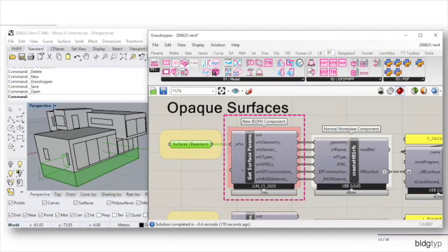This is going to be done by using a lot of these new Grasshopper components, and these things are used in line with the existing Honeybee components. So in order to extend and expand the basic Honeybee workflow, we're going to add some new functionality. For instance, when we create a new thermal zone, before you pass that geometry into the normal Honeybee components, we first pass it through one of these new IDF2PH tools. This is going to add a whole bunch of new information, a whole bunch of new classes, a whole bunch of new methods and functions to those objects. It's going to add a bunch of new intelligence and a bunch of new functionality to those objects.